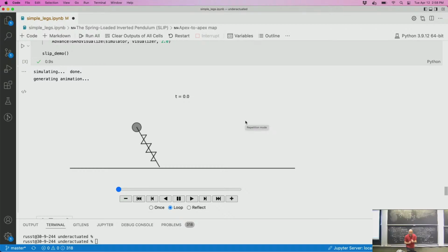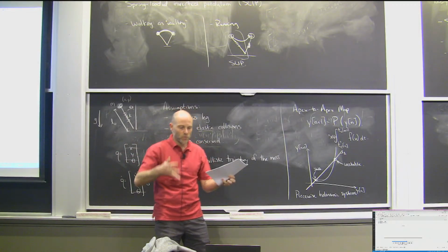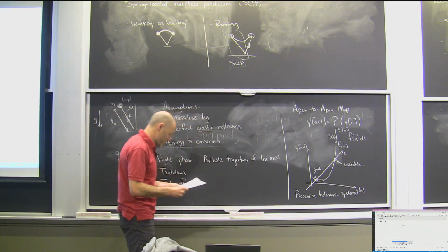And this is what it does. I pick some initial condition, I pick some stiffness of the leg, I give it some initial position and velocity, and I simulate it, and it runs stably, okay, with that projection trick. From small changes in initial condition, it will converge to this steady state hopping. Okay, and that was the model that, combined with the compass gait, gave us the spring mass walkers, which was kind of a nice putting it all together.